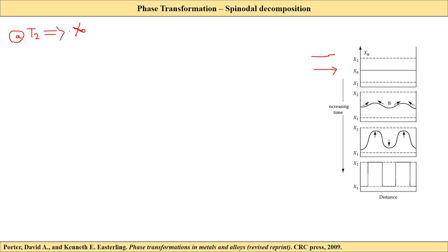For example, pure A has 2.01 angstroms, and B has 2.04 angstroms. So that is a change in lattice parameter. Now, if I try to add more B atoms, then the lattice parameter of A will try to increase, right, from 2.01 to 2.012, 2.014. So it will try to increase, and when I have total pure B, it will reach the lattice parameter of pure B, right?